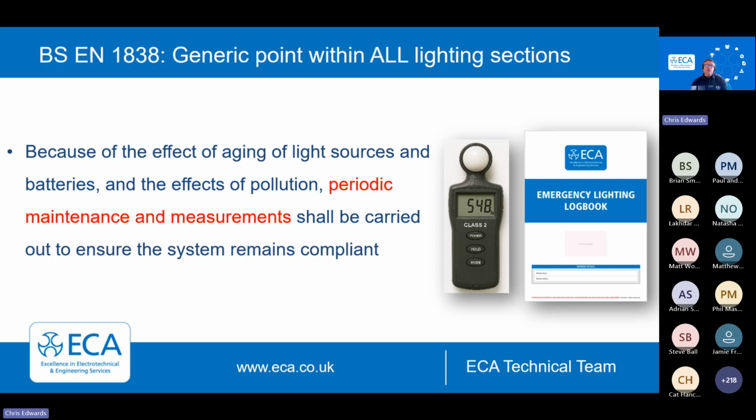The installation conditions could mean that the luminaires become dirtier and dirtier over time, particularly if there's no maintenance, and therefore when you need them to operate, either the battery isn't going to last for as long as it ought to, it may not have the same output as it once was designed for, or indeed the light is so filthy that it's offering no light for you to get out or see where you're going. It's those sort of things. So there's recognition throughout all of these. Actually, we really need to make sure these emergency lighting systems do what they do when we need them.